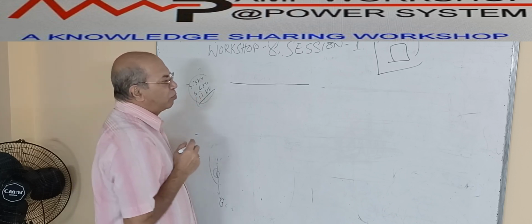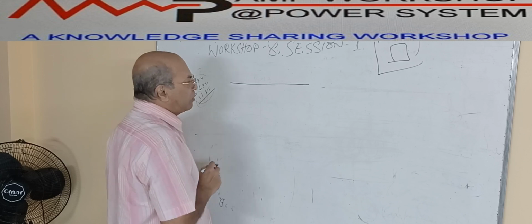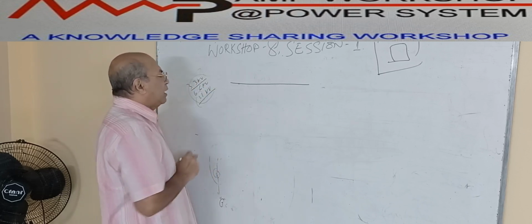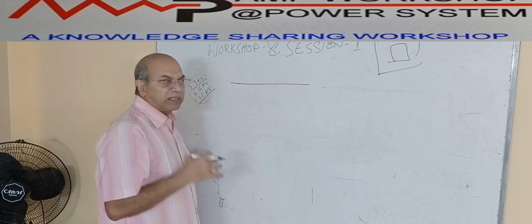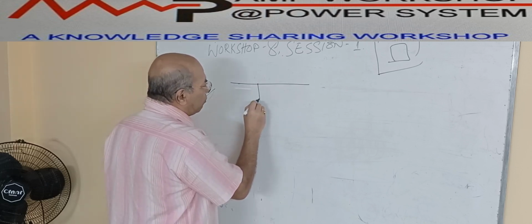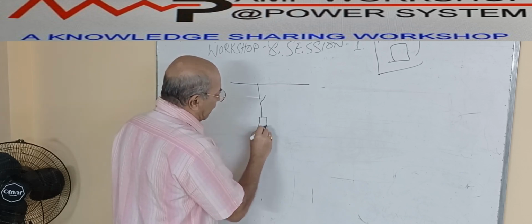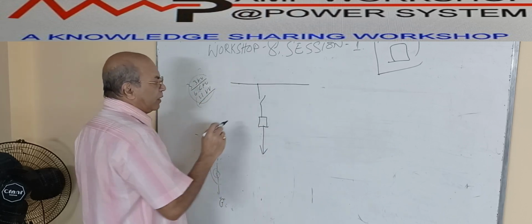To get the drawout feature, what do we do? Suppose this is a 3.3 kV switchgear; generally we do not use drawout. If in the case of 3.3 kV switchgear we need these disconnected or test features, what we do is put an isolator after the switchgear, then put the circuit breaker, and then it goes to the circuit.